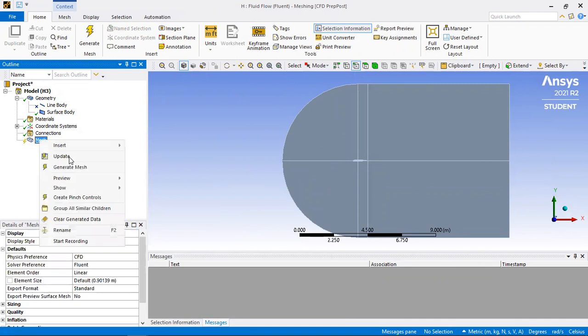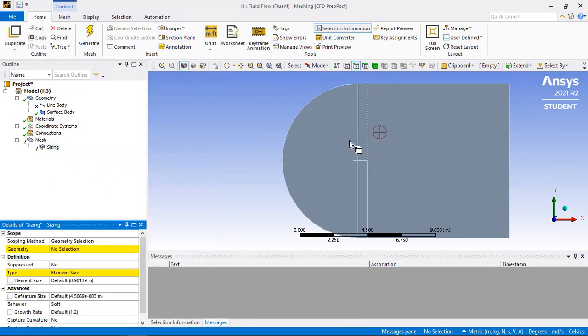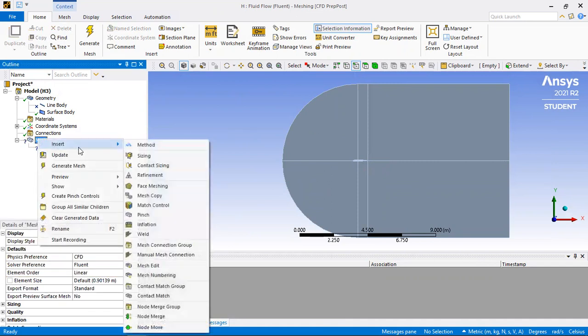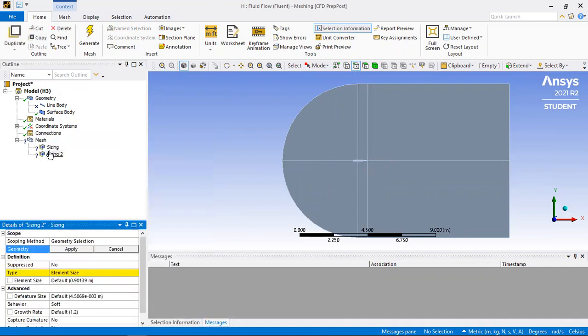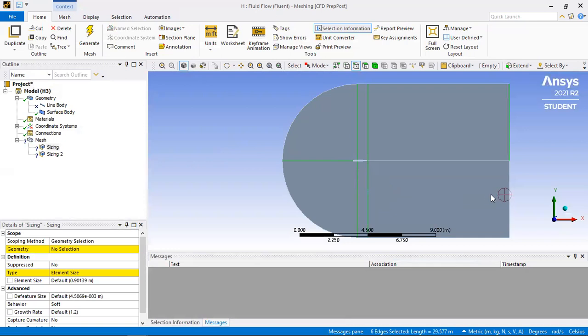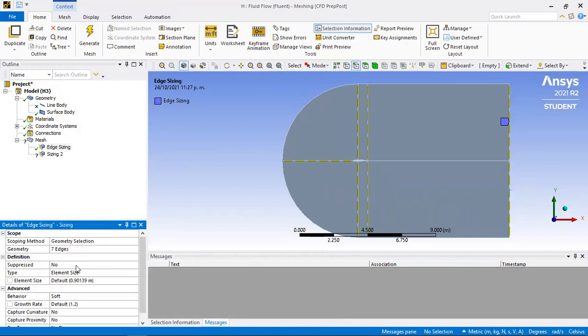Okay, so when making the mesh, we're gonna insert some sizing. This is to just have it really well defined. Okay, so in the first one, we're gonna select the same length edges. Well, they're not quite the same length, but almost the same. We apply to it. We define it by number of divisions. What we're gonna do is divide this, I believe, 200.